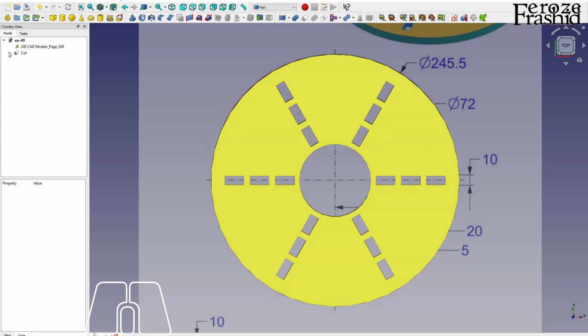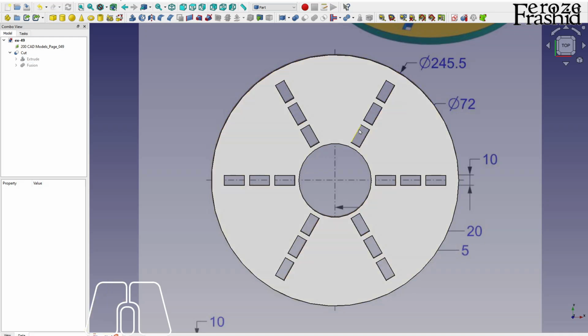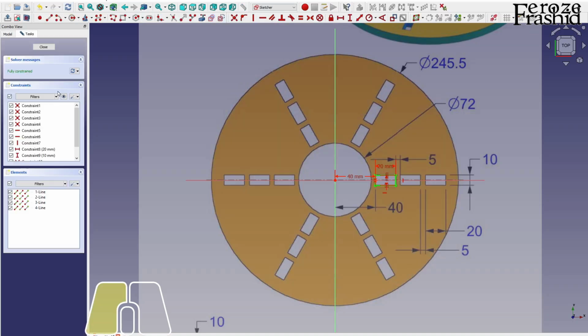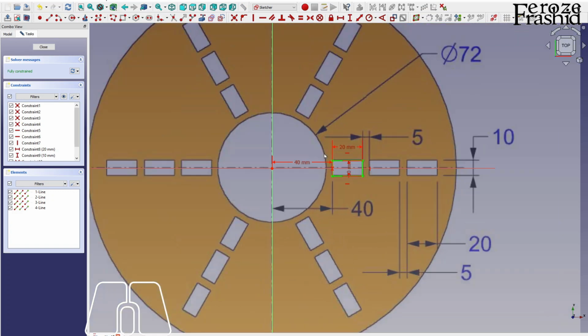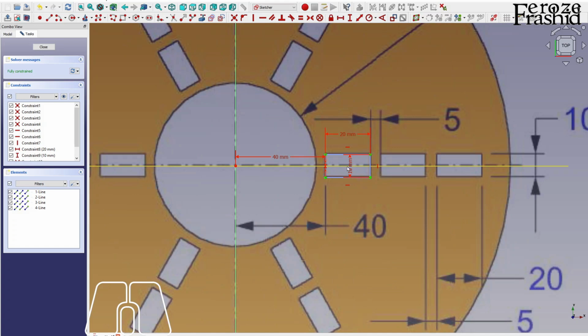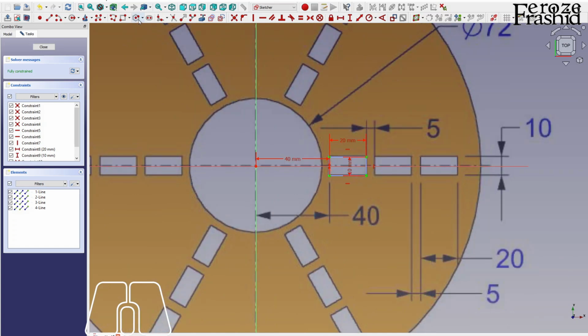Here, if I wanted to make those rectangular cuts in a circular one, I could trace that first sketch, that hole, right? From here and then make this one a different shape. So let me make that construction geometry, that way it doesn't show up. And for example, I wanted to say I want to make a pentagon or maybe hexagon.